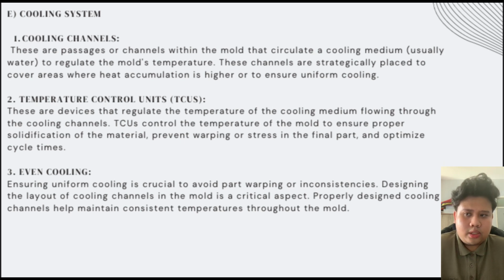Even cooling. Ensuring uniform cooling is crucial to avoid part warping or inconsistency. Designing the layout of cooling channels in the mold is a critical aspect. Properly designed cooling channels help maintain consistent temperature throughout the mold.